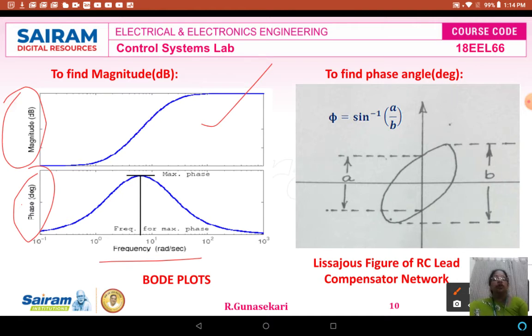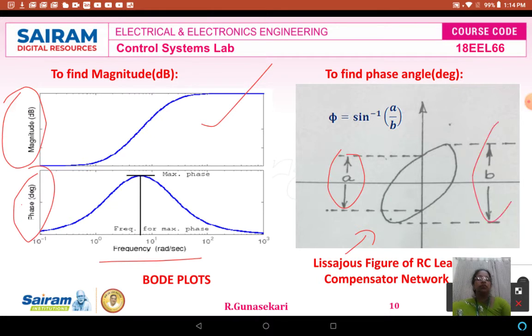This graph represents the Lissajous figure of the RC lead compensator network, obtained from a CRO. This is A, this is B. This is known as the Lissajous figure of the RC lead network. From this, how can we calculate the phase angle? Phi is sine inverse of A by B. A and B are calculated from the CRO values.